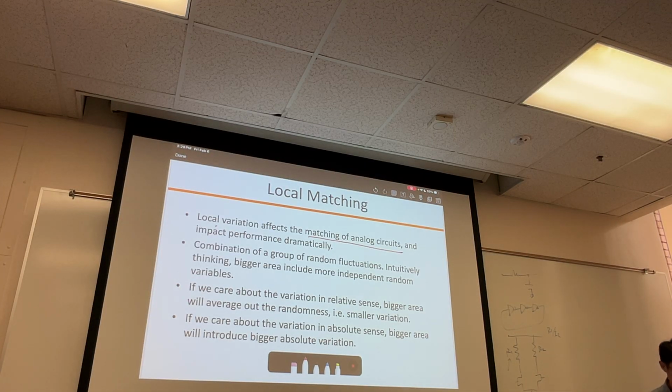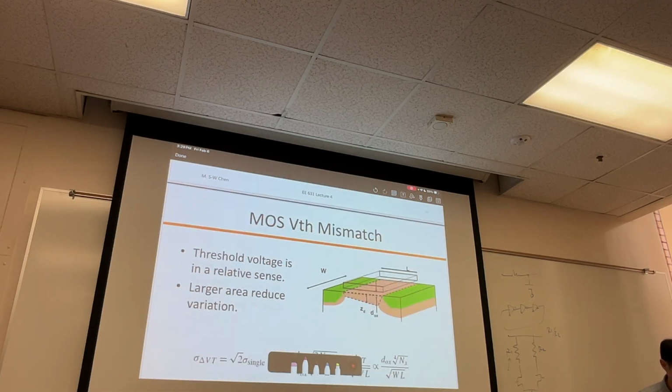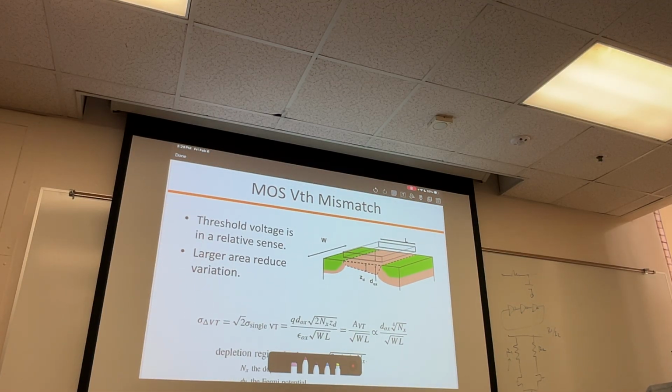This is a resistor, and of course with transistors, even if you make them side by side, they won't be exactly the same. One of the most important, as you know, is the MOSFET threshold voltage, which changes a lot of your behavior because your IV relationship is dictated largely by the threshold voltage. So the threshold voltage difference of the MOSFET is one of our big concerns.